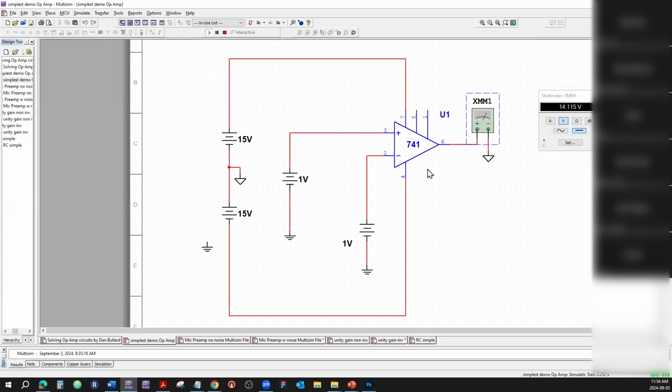There's always going to be a certain slight amount because of the voltage gain, the open loop gain. Open loop means there is no feedback between the output and the inputs. If it's an open loop, then the gain is ideally infinite. Is it? Well, it is. It's striving to be infinite. But where are the limits? Well, the power supply is the limit.